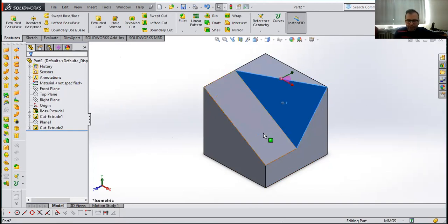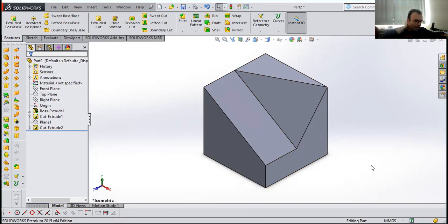This plane is developed, and then we use the triangle to cut extrude this part. Okay, now it is clear we developed this part. Now I'm going to continue my work here, but if you check the paper, in the paper we have a feature here, but the dimensions of the features are not clearly given. That's why we have to be very careful on selection of the plane.